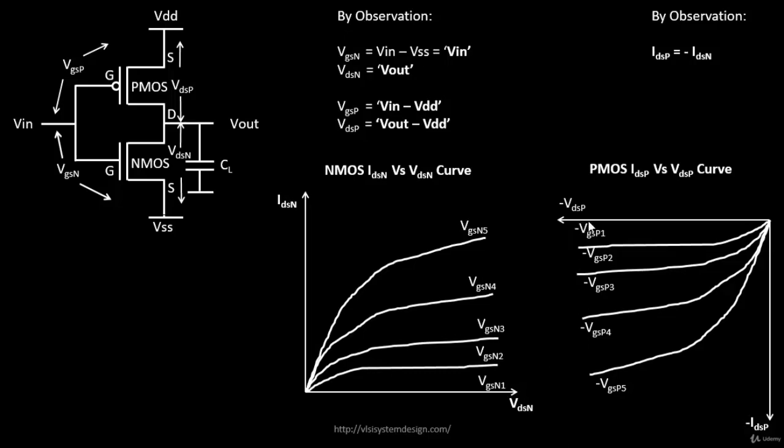But in this case, if you see, at a negative VGSP which is less than negative VT, where negative VT is the threshold voltage of your PMOS, it turns off and there is zero drain current. Okay, and as and when you increase your negative VGSP, or basically take VGSP towards the more negative side, it becomes more and more lesser than the negative threshold voltage of PMOS.